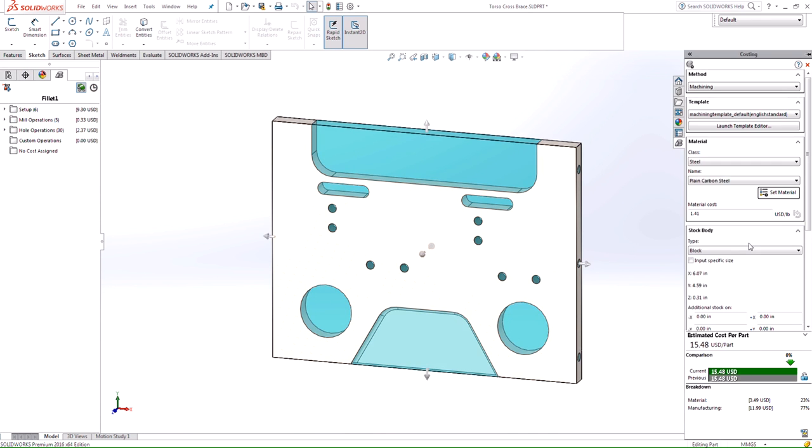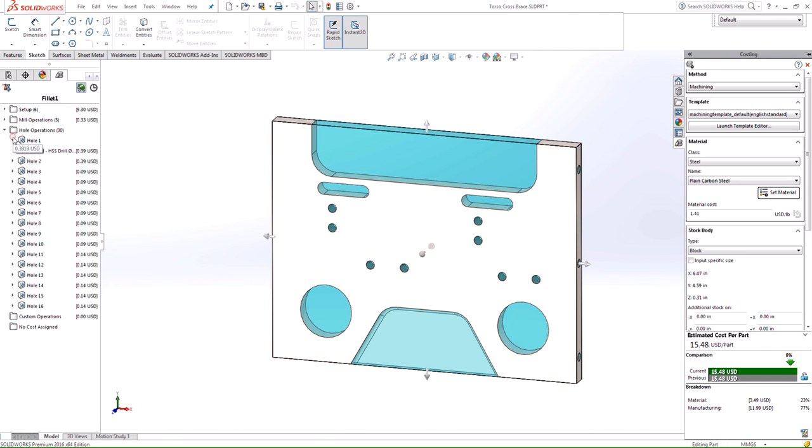As we know, the costing template is where we define specific machining operations, specific hole size operations, and things like that. What we needed to do is, I drilled out some holes within this part, and when we go to the hole operations, it told us with the warning symbol that we don't have an actual hole size to accommodate that drilled hole.